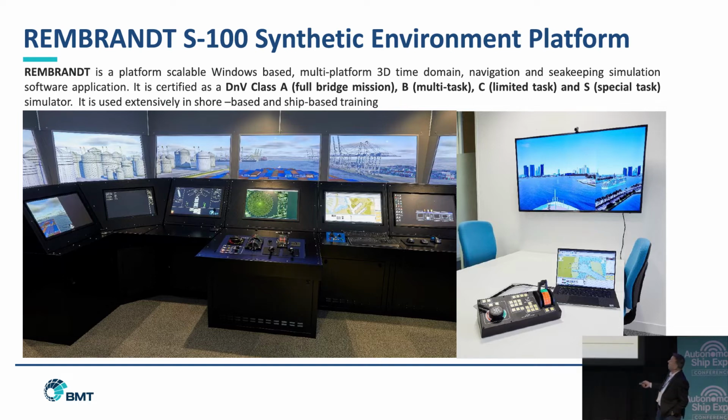It's standard stuff: full 6 degrees of freedom, 2D and 3D dynamic current flows, squat, bank and ship-to-ship interactions, and ENC platforms that automatically generate the interactive topography and bathymetry. It's also AIS enabled, VDR and PPU enabled for pilots, and it has a very rudimentary decision-making interface.